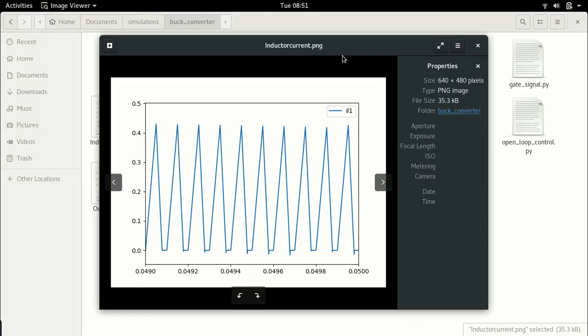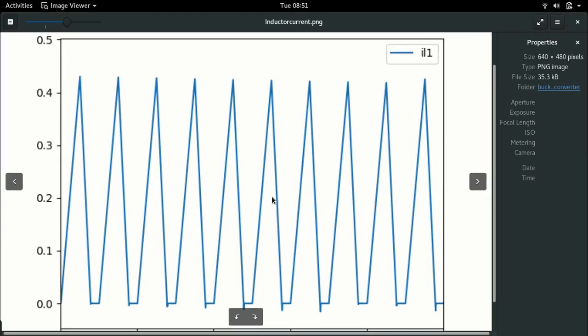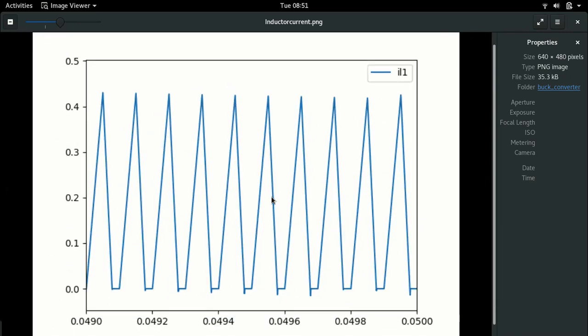And you see this is what happened. Really speaking, what we saw before was actually just a plotting inaccuracy. We had this feeling that the current was negative, and that's one of the reasons why I wanted to investigate. It's actually not negative. What is actually happening is this little spike here is when the diode turns off, right? And like I said, this is discontinuous conduction mode. Just check out what's happening. When the inductor current increases, that's when the switch is turned on. When the switch is turned off, the inductor current drops, and here it falls to 0, and this is when the diode turns off.